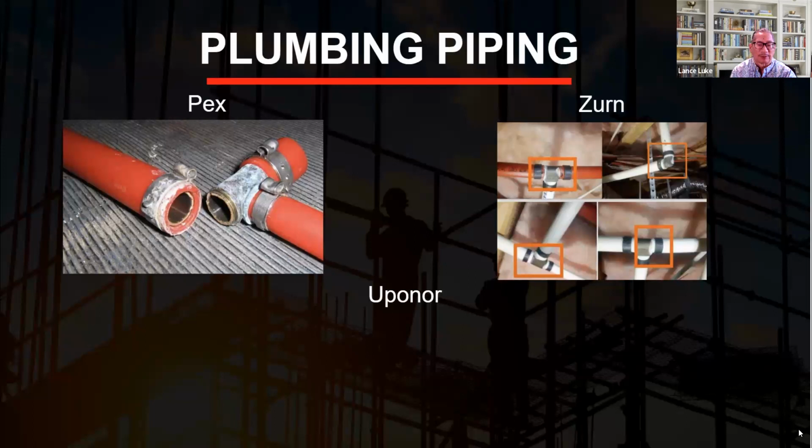Now there's thousands of houses in the United States, like Las Vegas and Arizona and other areas, where they plumb the single-family houses with PEX piping. A lot of them have been replaced already because of the failure of the connectors. Yeah, in some cases, the plastic even ruptures or cracks, or just doesn't do its job. So that's the plumbing as a defective building product.